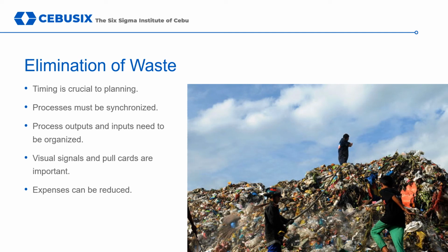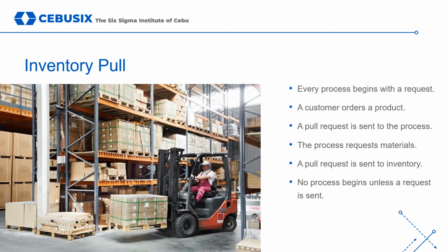Just-in-time cannot exist when there is too much waste within a process, as it is more sensitive to variations than batch processing. While most organizations up until the 1990s operated using a push system where production was based on a forecasted future demand and a warehousing of excess inventory, more and more companies have been implementing just-in-time manufacturing because its pull system is more efficient and tends to result in higher quality outputs.